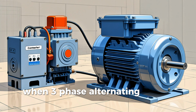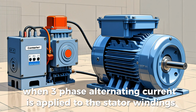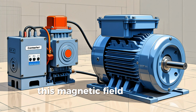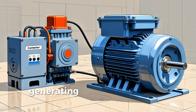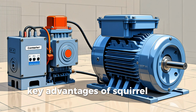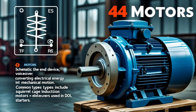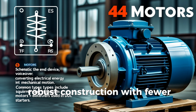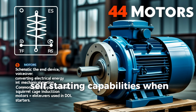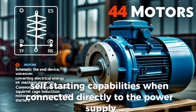When three-phase alternating current is applied to the stator windings, a rotating magnetic field is produced. This magnetic field induces current in the rotor bars, generating torque and causing the rotor to turn. Key advantages of squirrel cage induction motors include robust construction with fewer moving parts, low cost and ease of maintenance, high efficiency and reliability, and self-starting capabilities when connected directly to the power supply.